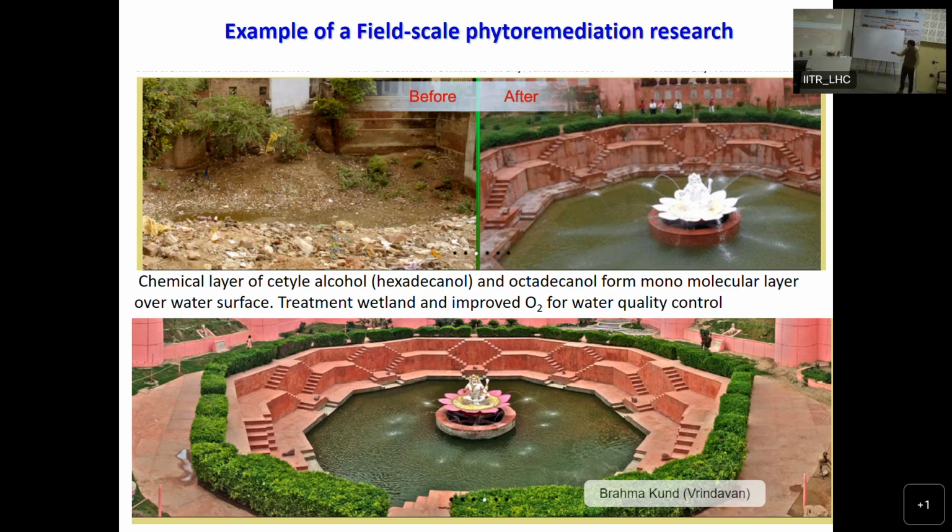And local plants were also provided. These plants are not for beautification, but the idea was that these plants interact with the water which is filled in this pond. So the idea was to make use of these plants for the water quality improvement of these ponds, because it's not flowing water, it's almost stagnant water. Groundwater table is deeper. But plants are not magicians. You cannot say that one or two plants can do everything. No. As compared to the volume of the water, the plants were not sufficient to improve the water quality.